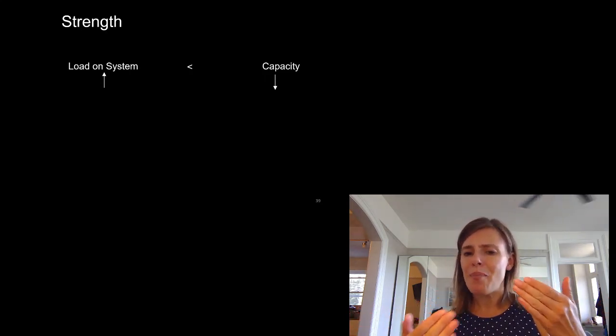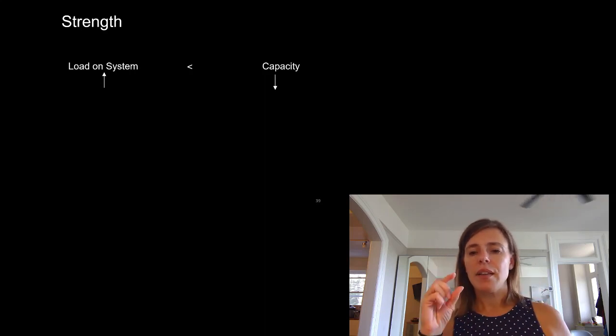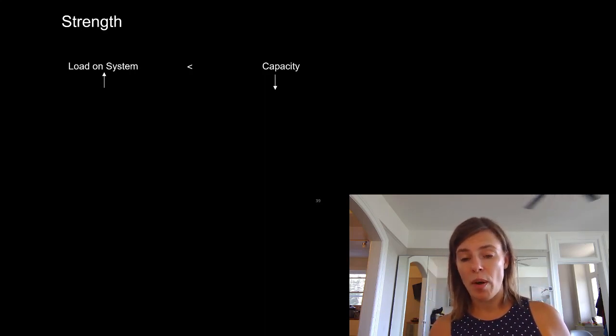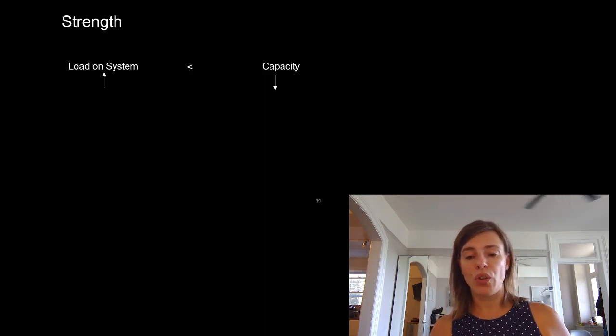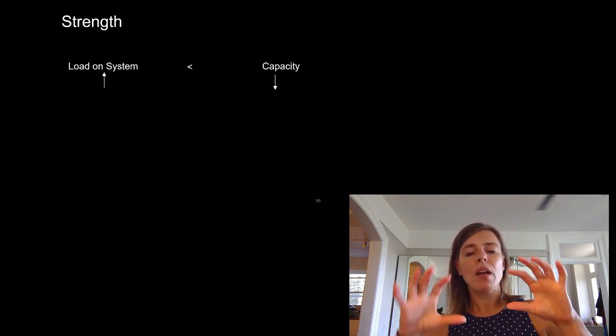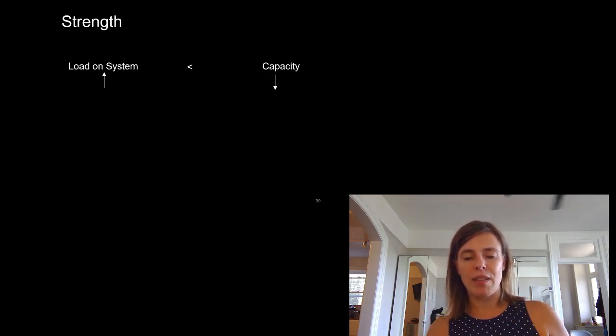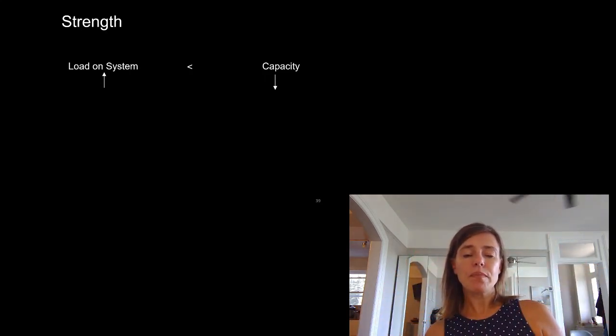We want to build in a buffer there anyway, so it might have a smaller increase than Shannon, because we don't know if Shannon's going to go out and have a cheeseburger and beer, or if she's going to go out and have a whole turkey dinner with all the fixings. So we want to build a different amount of buffer in for those two different loads that are going to be acting on the table. It's self-weight and Shannon climbing on top of it.